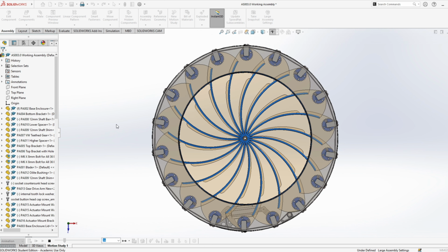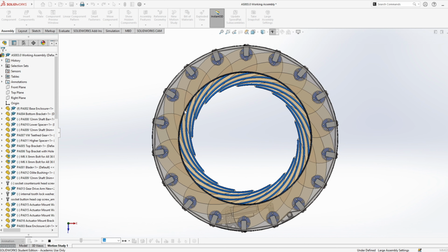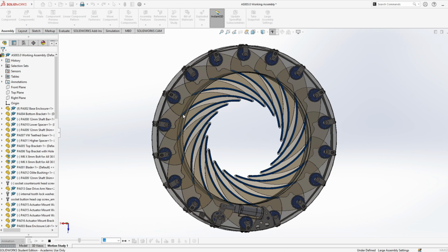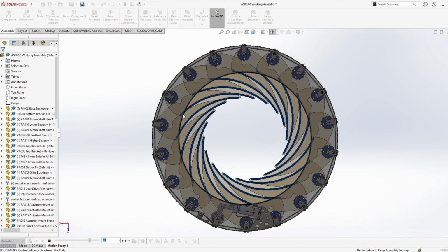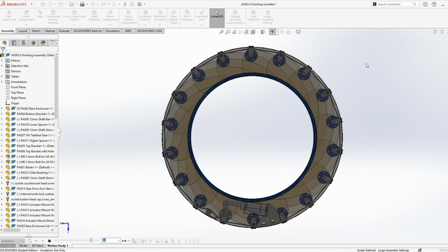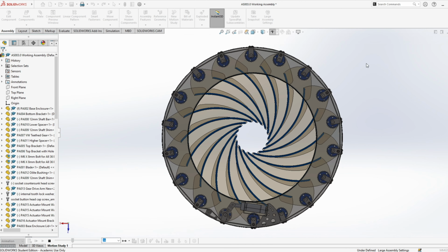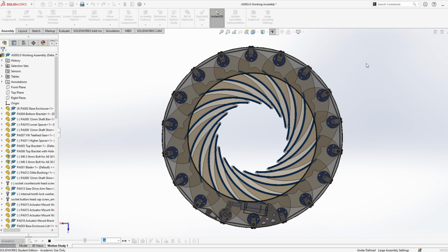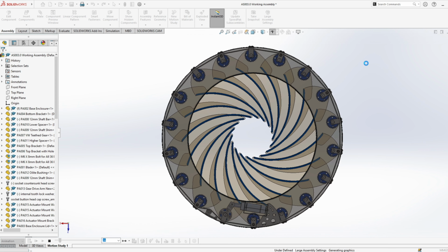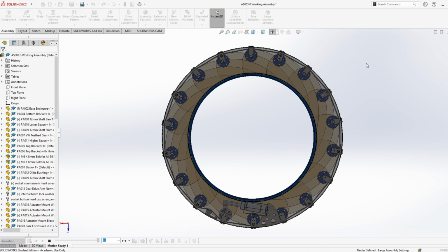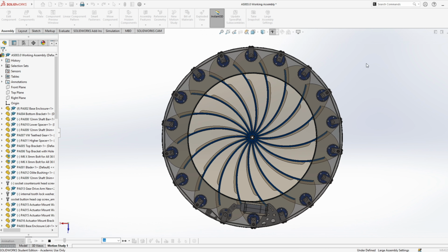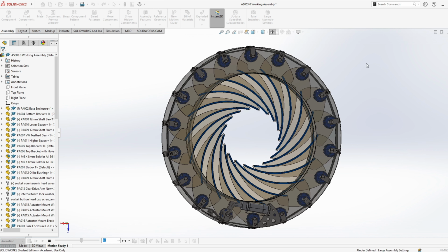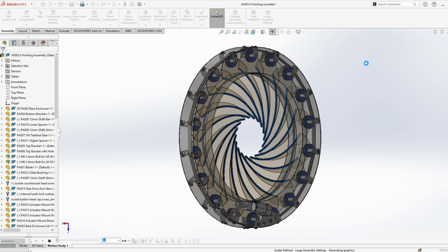So you can see here how the diaphragm fully retracts into this enclosure at the front face and at the interior face, the interior side. As mentioned earlier, these blades in this project are designed to be curved, to blend or fall back into the compact enclosure or the surround seen here. So if these blades were straight, it would result in a definite polygon shape at the diaphragm's opening. Therefore, curved blades improve the overall roundness of the iris opening seen here.